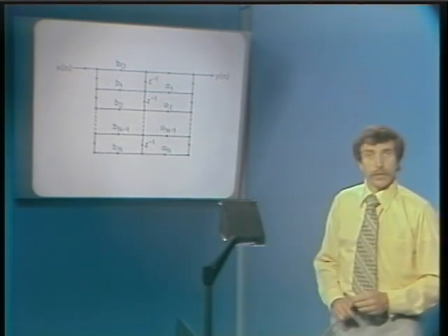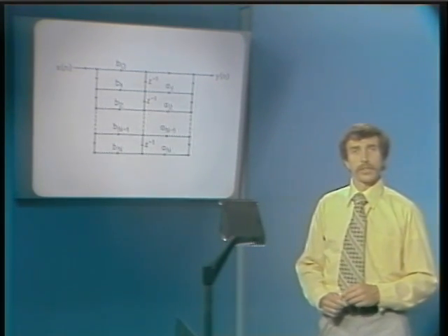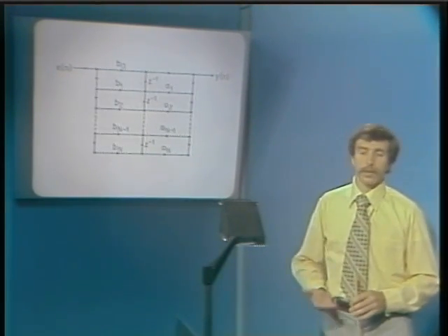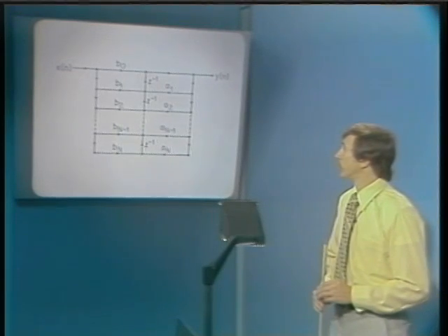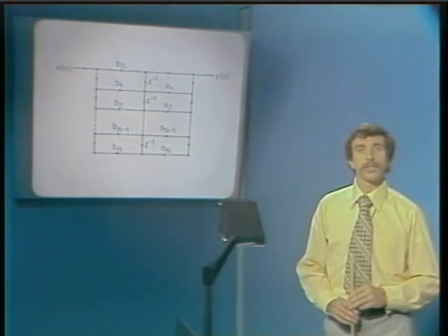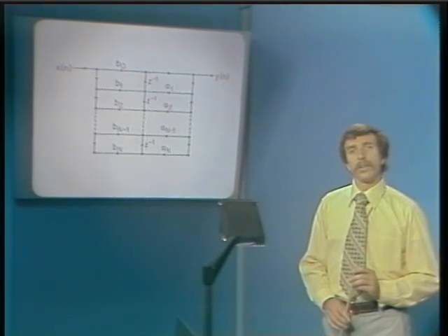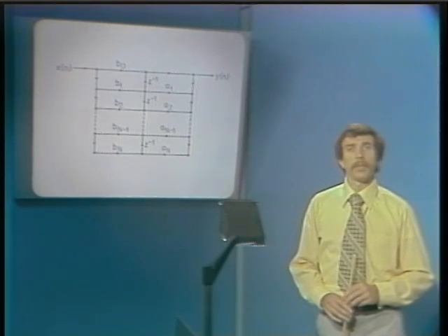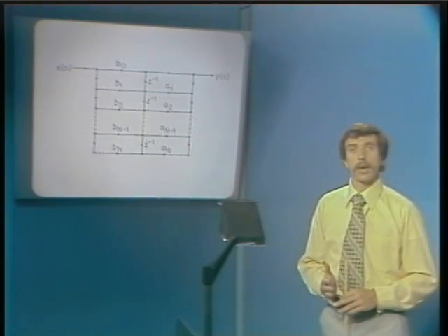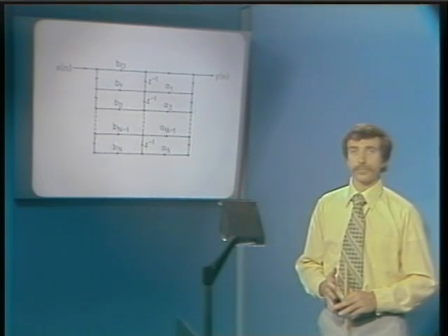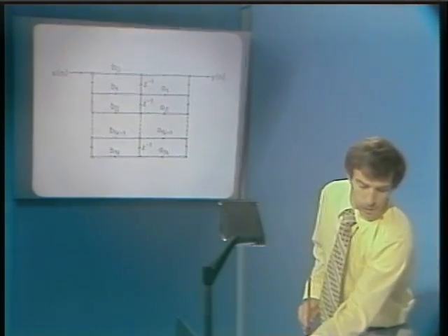Well, these structures are fine for implementing the difference equation, although there are other structures. Actually, there are essentially an infinite variety of structures, but there are some other structures that in some situations are better to use than the direct form structures. And two of the more common, which I'd like to introduce now, are the cascade structure and the parallel structure. The cascade structure is developed